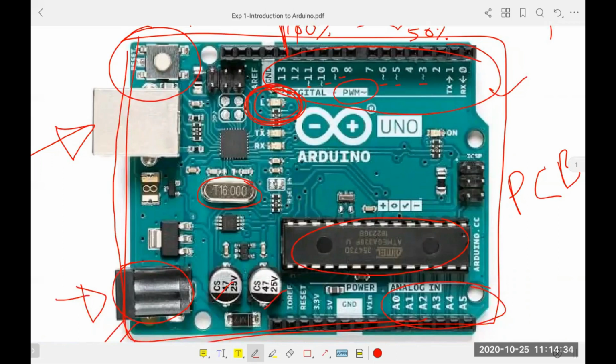Sometimes we need this whenever we find any anomaly, then we give it a reset, just like our computer restart. Anyway, here is also a reset pin. So using this reset pin, this could be active low or high. You should check this from the data sheet. By using this reset pin, you can also reset the Arduino board with a proper signal.